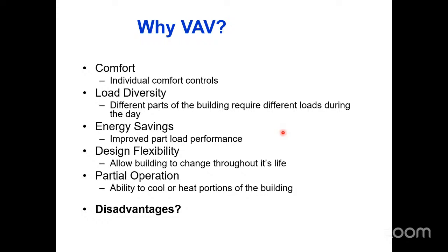It is pretty flexible. It is not impossible. In fact, it's fairly common to design an air loop that goes around one floor of a building without knowing what the tenants are going to be on that floor yet. And then as the tenants move in, the ducts can be tapped off of that loop to provide air in certain quantities to certain areas depending on what's going on in that particular zone. So it is pretty easy to expand and adapt that system by tapping new zones in off the ductwork.